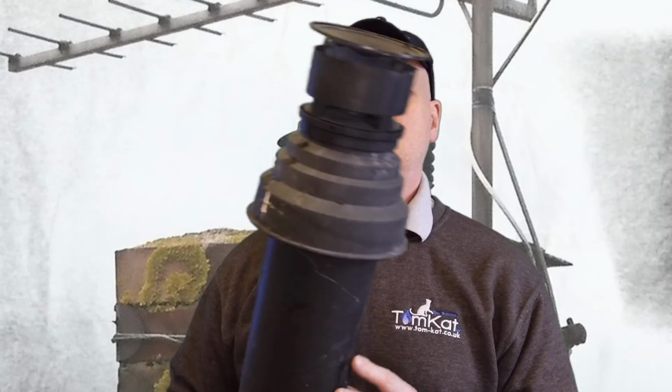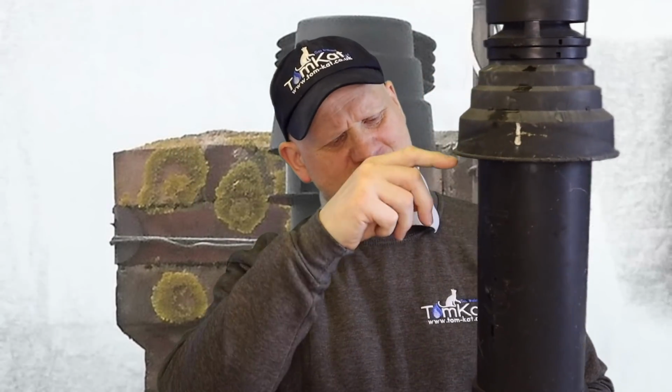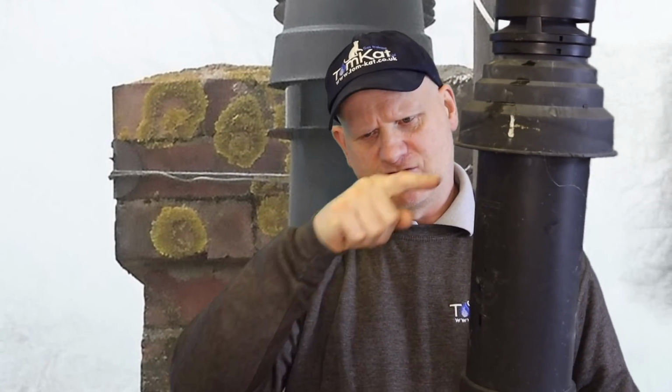And the last flue type we're going to be looking at is the vertical flue system. So this is probably the least liked installation of any gas engineer, because you've got to get on the roof to do it. Now this black part of the flue is a set height. Now some manufacturers say it should be 300 from here to the pitch of the roof. Some say it's 400 on the angle of the pitch of the roof.